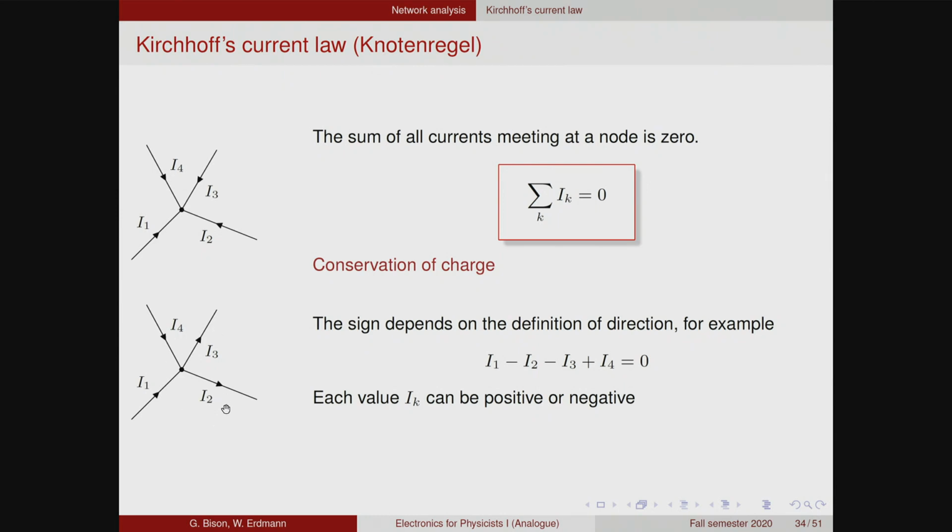What you would typically do is, when you draw a schematic, you define the current direction by indicating arrows. And then you calculate what's going on, and it can be that the current that results actually flows in the other direction. And this simply means that the current that you have at a certain segment is negative.